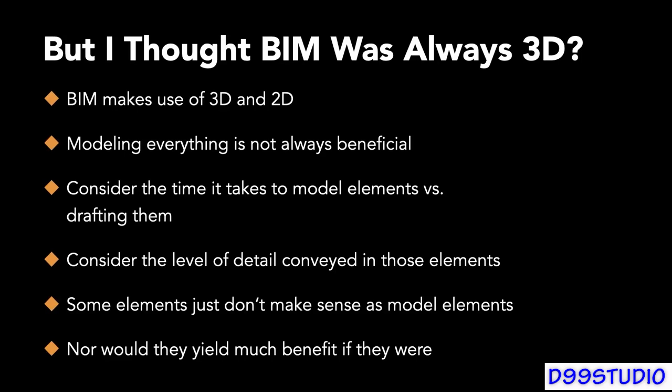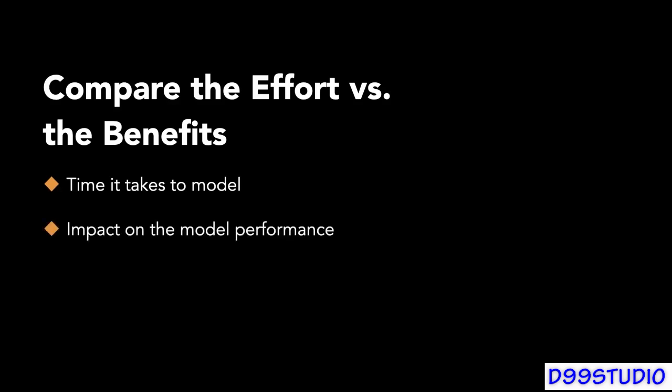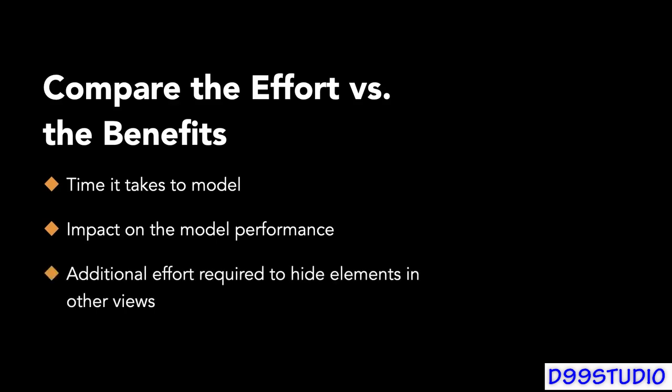It's true BIM. The trouble with this line of thinking is that the amount of effort that would be required to create all of those kinds of items and the time spent doing so would not really yield much payoff. Furthermore, you're creating a lot of extra detail and a lot of extra weight in the model that will potentially slow things down and take a hit on the model performance and the processing power that's required in your computer system. And in many views, you're going to want to hide all that extra information because it doesn't contribute anything to that view.